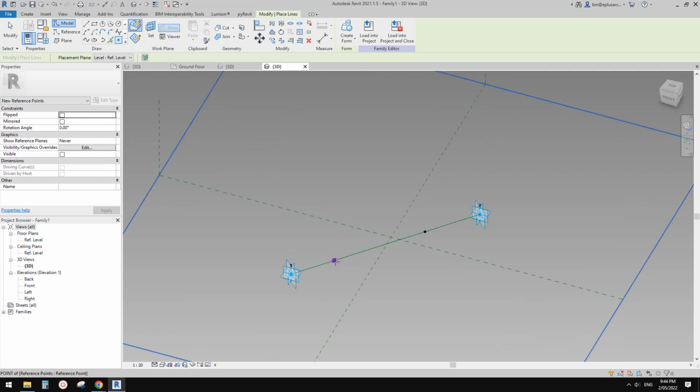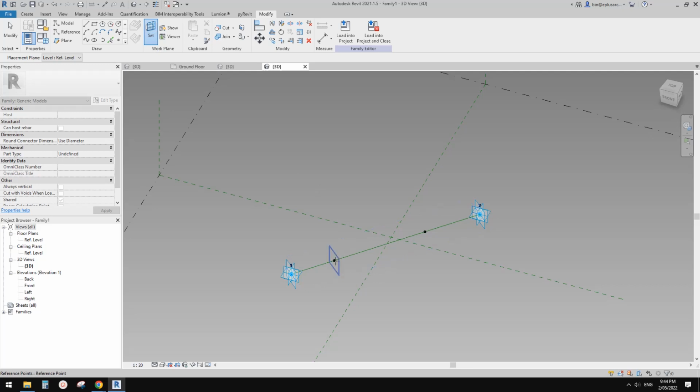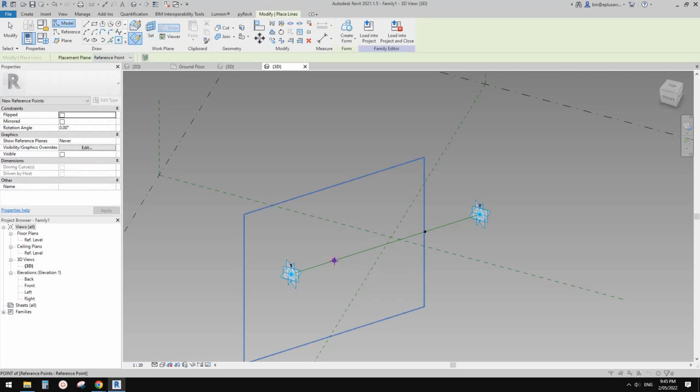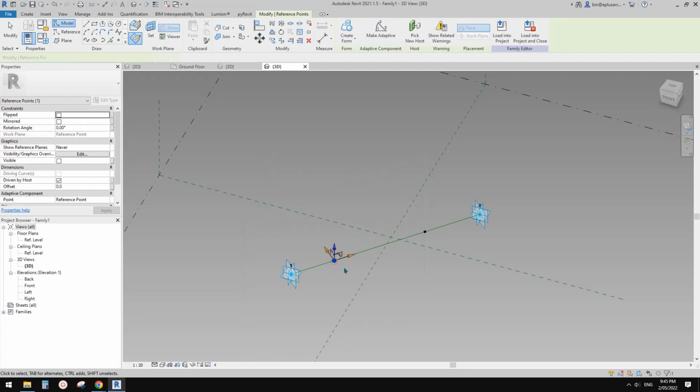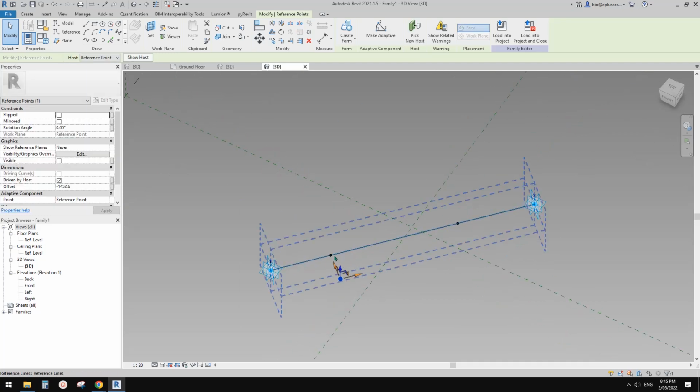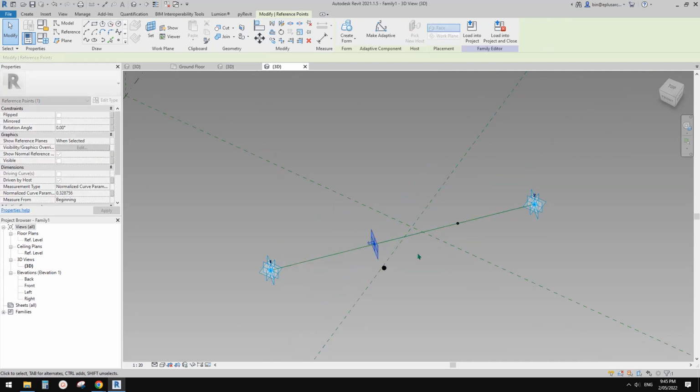So, and then from this point, we're going to offset it. Okay, so create another point, offset from this point. So draw point, draw on face, oh, sorry. Point, draw on work plane, set work plane, and pick the vertical work plane. Okay, and then place it on this point, and then OK. So now select this point. So for this one, I think I want it to go this way. Okay, and also you can adjust the point along this reference line.